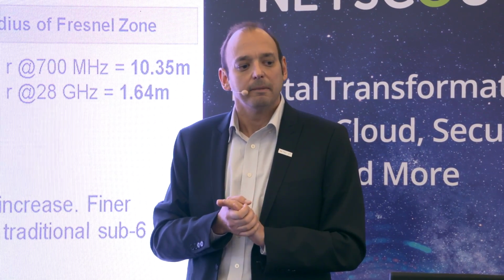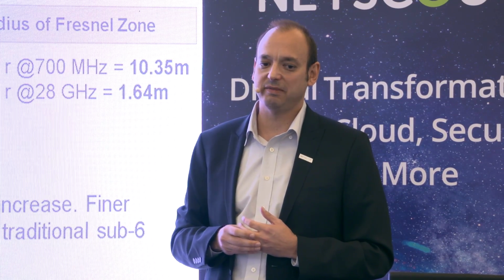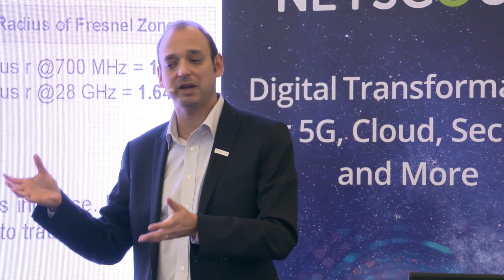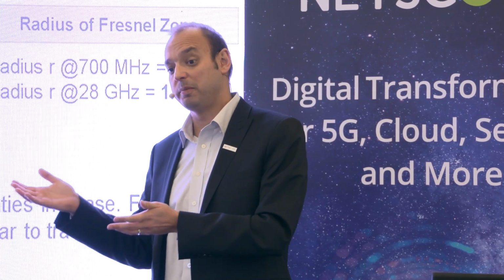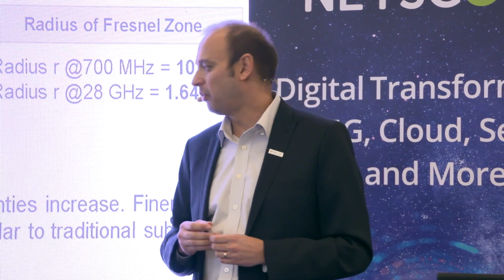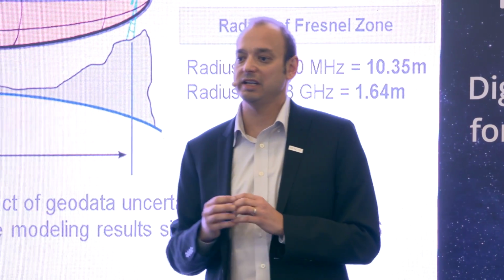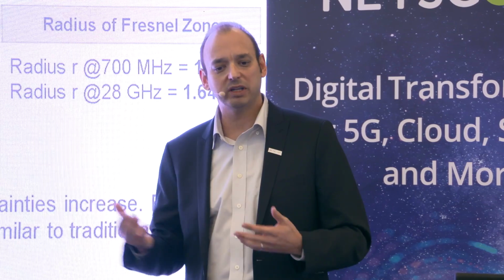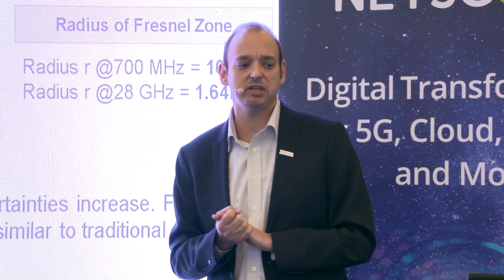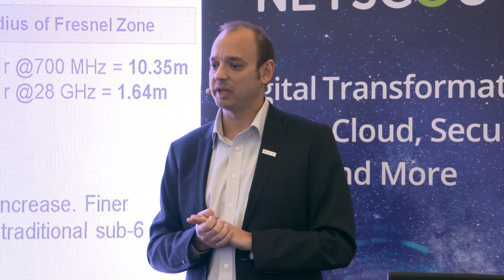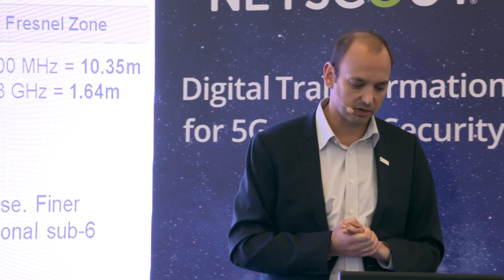But nowadays, for 5G, most of the geodata that's available and what's recommended is actually in the form of a vector. So it comes in the three-dimensional shape of a building, or three-dimensional shape of a vegetation or tree. And one thing to understand is what are the inputs that go into that? Is it the satellite images? Is it the LiDAR? Or what kind of accuracy do they have? These are all conversations that you should have with the geodata vendor, and consider that for your millimeter wave design, because they have a pretty significant impact on your coverage.